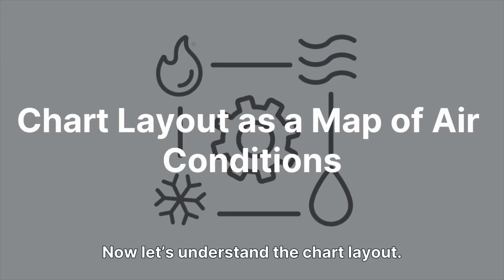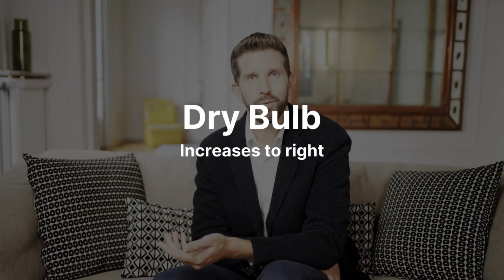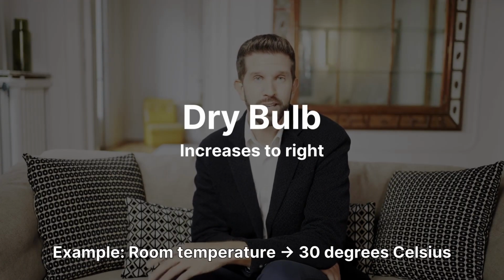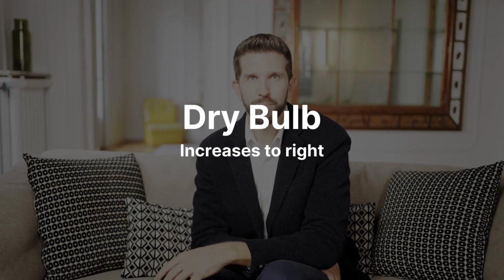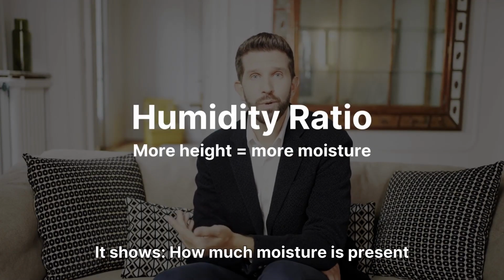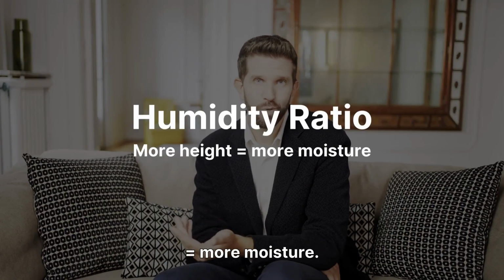Now let's understand the chart layout. Think of it like a map of air conditions. The horizontal line is called dry bulb temperature. This is normal temperature, the temperature you see on a thermometer. Example, room temperature 30 degrees Celsius. When temperature increases, we move right on the chart. The vertical line is called humidity ratio. It shows how much moisture is present in the air. Units: kg of water per kg of dry air. More height equals more moisture.